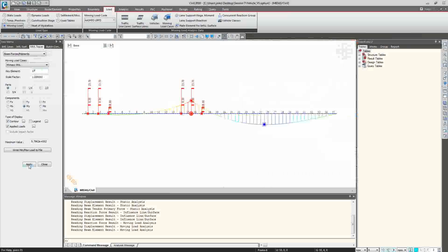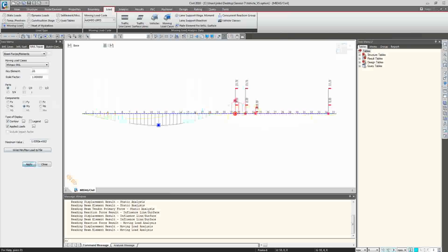So I check 17, and when I check on the other side, it's even larger, and it comes back. So it depends on the selected elements. The varying space allows the program to calculate individual loading effects and then displays the worst case scenario. It displays the vehicle location for the worst case scenario.